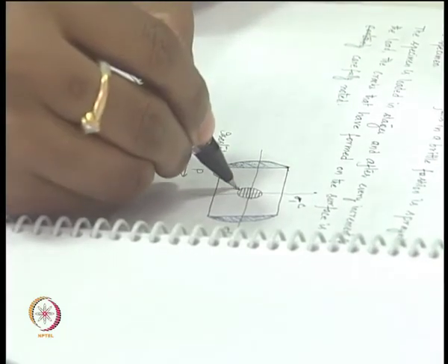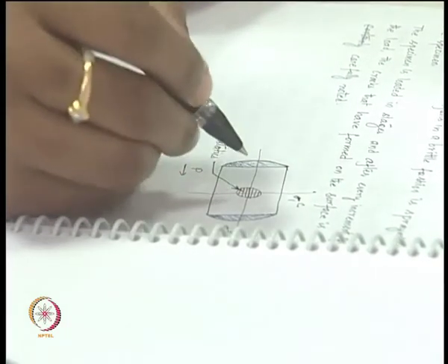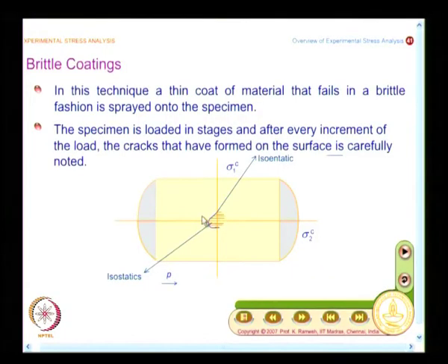So, what you have here is, you apply the load, go and look at the formation of cracks, mark the boundary, then come back and increase the load. So, you will do the loading intermittently, in between you have to go inspect the cracks, and there are many methods developed for how to identify the cracks. You should not let cracks on the structure escape attention. So, you have to inspect the complete structure.